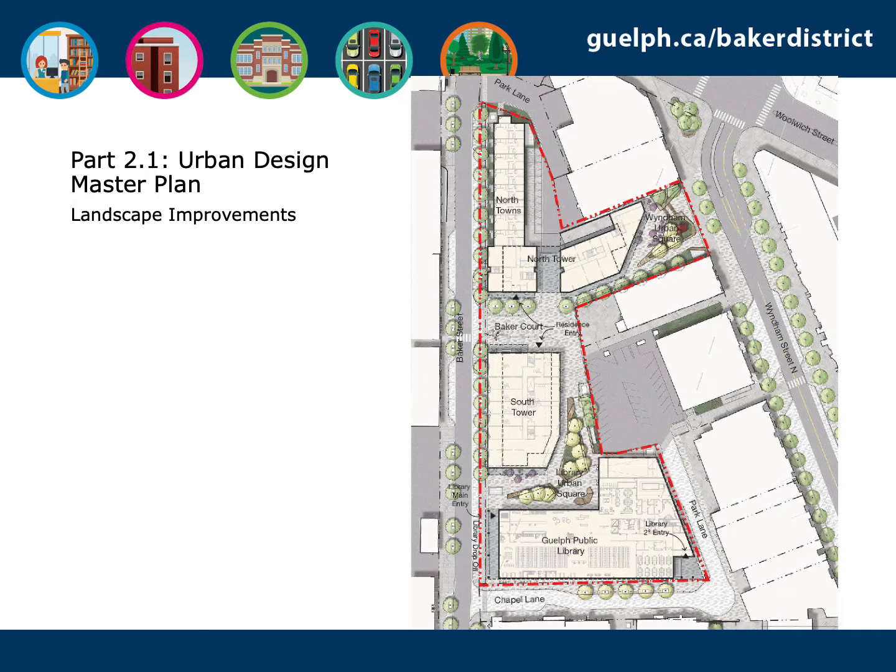To support the redevelopment, Baker Street will be converted to a 2-lane, 2-way, flexible street not unlike Wilson Street in downtown Guelph. It is assumed to be approximately 18 meters in width, with parking on either side, and incorporating street trees and an expanded public realm.